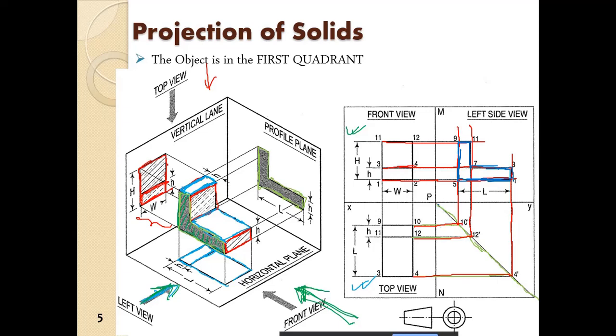Now here you can draw a 45-degree line, or from this point you can also use arcs. Okay, so there are two ways to find out the left hand side view if you are asked for it. So, front view, this is the front view.